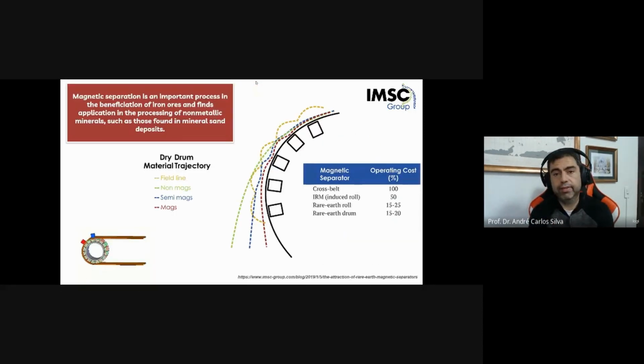and then you go to your lab and perform some tests. Okay, so again, I bring back to you the same picture from the beginning of our presentations of this material, and I'm going to show you a little bit how the material is going to be separated at the tip of our conveyor belt. You have magnetic blocks and non-magnetic blocks. They are all connected together, and then you have a slight change in the particle trajectory, but that's enough to change where your material is going to land on one side or the other of our splitter.